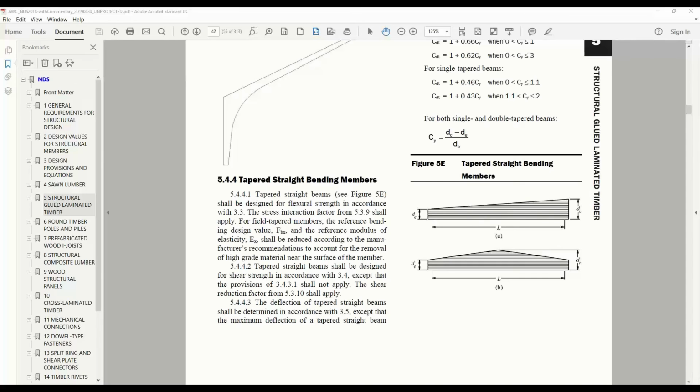We do a lot of picnic pavilions where it's a cantilevered column system. So the columns are buried about 4 feet in the footings of the slab. So we have that higher retention rate for direct ground contact. Yeah, that's not unusual. I think you can get glulams treated even with non-CCA products for ground contact. Many manufacturers will develop and treat product for that type of use.